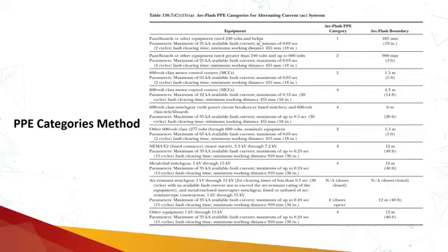If any of these conditions are not met, we cannot use this information. For example, in my industry, the panel board and other equipment is operating at 240 volts. The maximum available fault current in my industry is 30 kiloampere. So I cannot use it because here they say that the maximum available current should be 25 kiloampere.